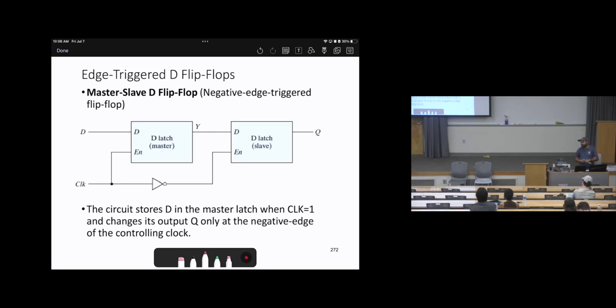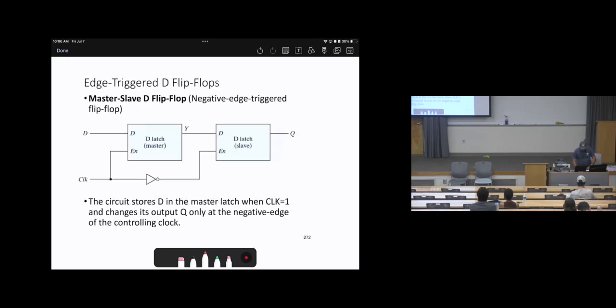Then we replaced one of these by NOR gates, then the other one by NOR gates to create SR latches. Then we added enable. Then we said S and R is undesired because we have a forbidden state. Then we can create D latches with enable. After that, we said the latch is not preferred, so we need to create flip-flops, which are a combination of two latches. We are climbing the hill, going more complicated step by step. If you're not understanding the latch very well, then maybe you'll struggle with the flip-flops and so on. So please make sure to be up to date.